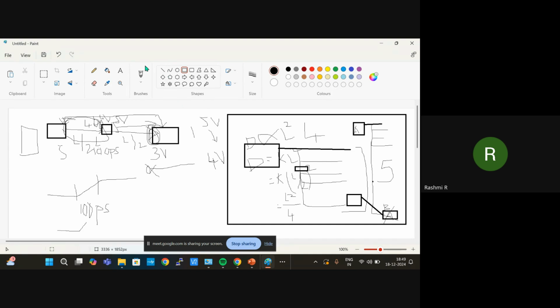Now this cell is driving this cell and this cell. The fan out of this cell is 3. Now this buffer is driving these three cells. So this fan out is also 3. So our fan out constraint now got resolved. It is obeying our max fan out constraint.